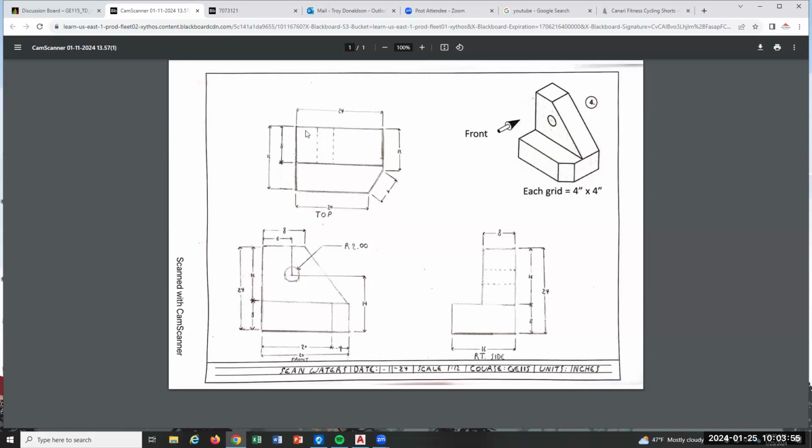These two are good. They're in projection. The hole projects over and makes hidden lines, hidden geometry, right? So every geometry, this edge projects over and creates something in the adjacent view. It's how you know you've got something over there. There's an edge or something that projects over.